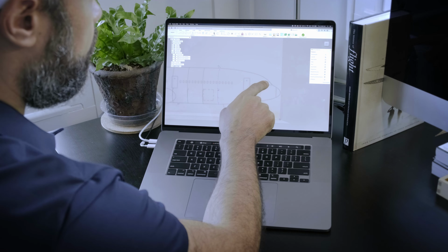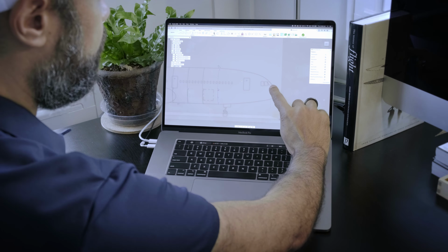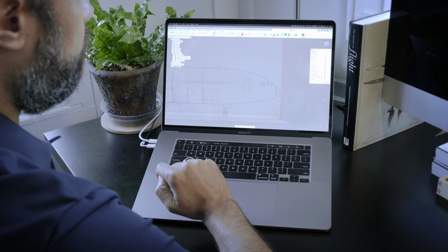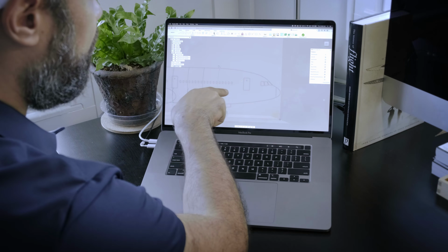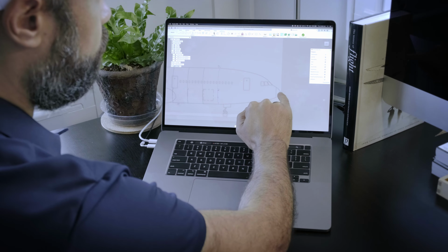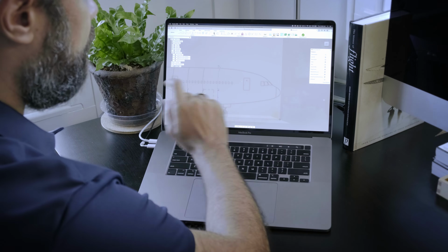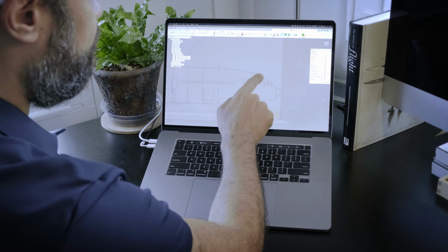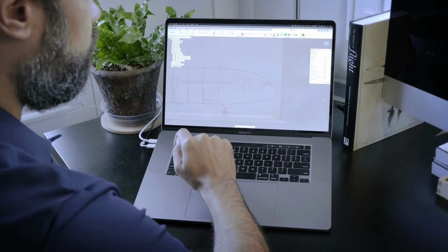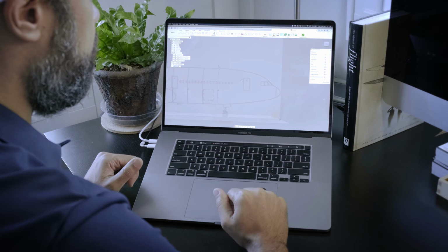One of the breaks is here at the top end of the window, and the other one is here at the bottom end of the window. Then we also have a midline, where the shape or the direction of the nose changes to go underneath the fuselage. And because of that, we need to create individual sketches for all of those in order to get our loft tool to make the shape that we need.